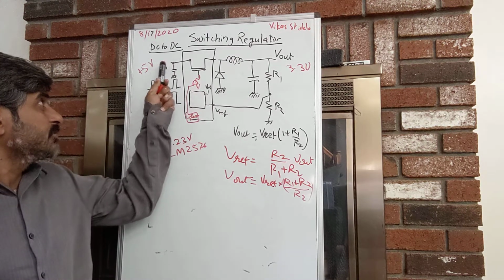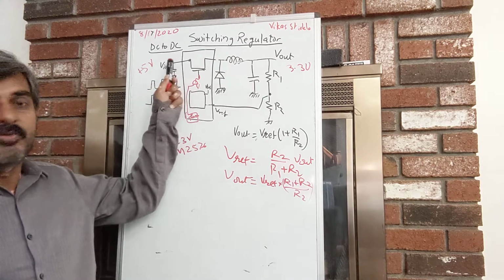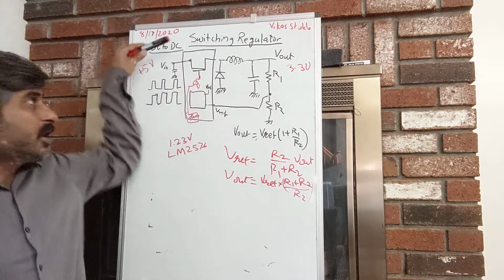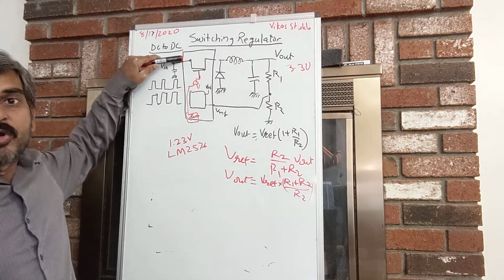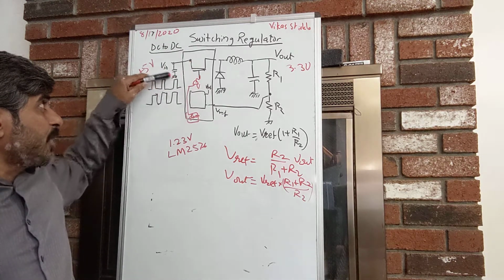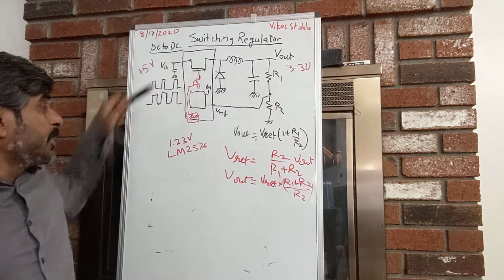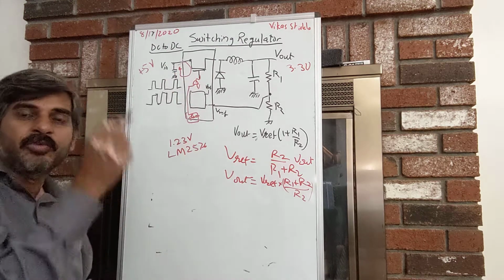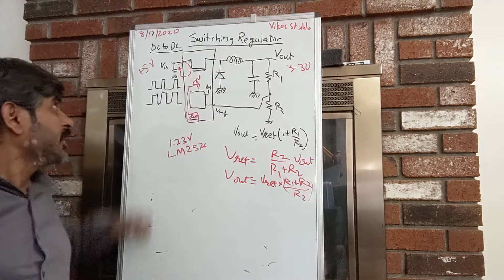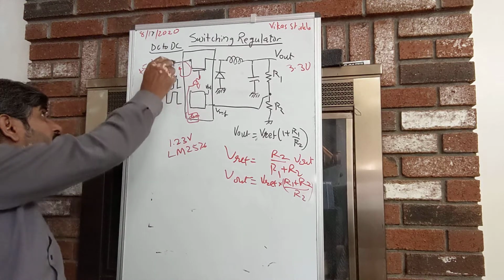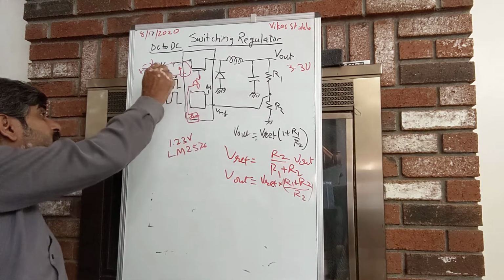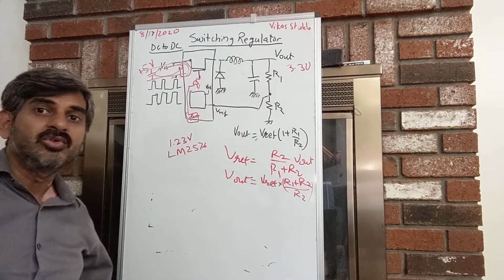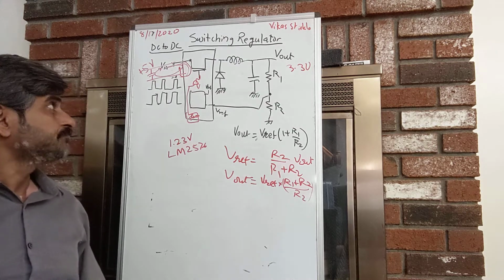The reason is that this input voltage is switching. You can think of this getting on and off, switching at a very high rate on this particular node. So it must have a return path, and depending upon the area of this loop, this forms a kind of antenna. If you place this capacitor in your layout at a very far place, then this loop gets bigger, and that bigger loop starts radiating, and then you have an EMI noise problem.